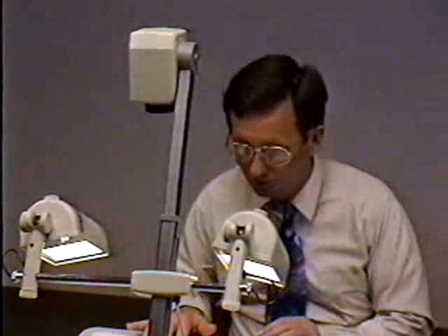That was talking about discharges. We can also talk about rainfall. And rainfall runoff modeling is necessary in a lot of design work because we have no stream gauges. The only way you can do a frequency analysis for gauge stream flow data is to have a stream gauging station.